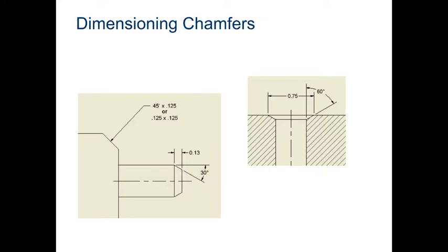We didn't talk about this yet. We haven't gone into this yet. Basically, the best way I can describe a chamfer is a lazy fillet. It is a flat fillet. All it does is it's a lot easier to machine a chamfer than it is to do a fillet. With a fillet, you have to figure out a radius, and then you have to take a chamfering or a radius or a fillet tool and actually cut away material. Now, when you're doing steel or really hard stuff, it's really expensive. You need diamond-tipped blades or diamond-tipped systems to do that. It's too much. So with chamfering, all they have to do is take one solid blade and go across the edge of a part.